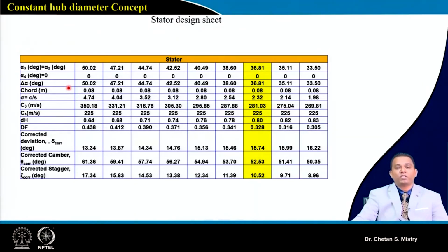Now here we are doing the calculation for one stage. Suppose we consider a low bypass ratio engine; for that we will have a number of fans, maybe one fan or maybe three fans, based on our design. So accordingly you may need to modify certain dimensions. When you change your dimensions, again you need to revisit this Excel sheet program, modify those parameters, reiterate, and come up with the final solution.